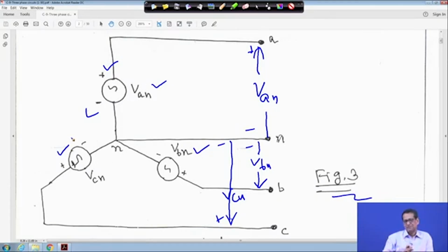So basically you have a magnet that is rotating, and it is surrounded by a static part called the stator, where windings are placed 120 degrees apart, right? As the magnet is rotating, voltage will be induced in all these three different coils, which are physically 120 degrees apart, right? And if you take, for example, the voltage induced in VAN as a reference, then VBN lags VAN by 120 degrees and VCN lags VBN by 120 degrees, otherwise VCN lags VAN by 240 degrees, right?